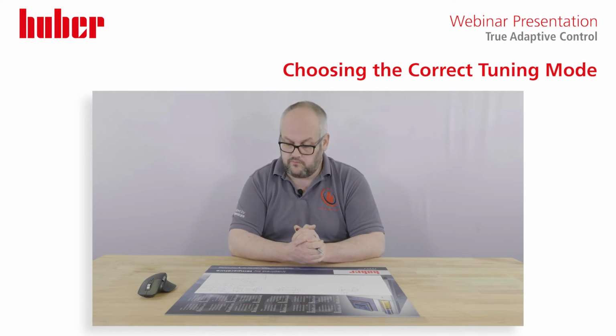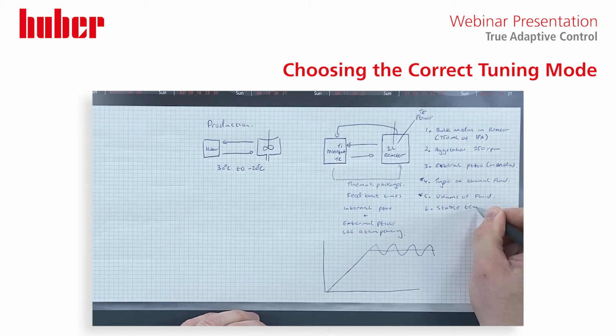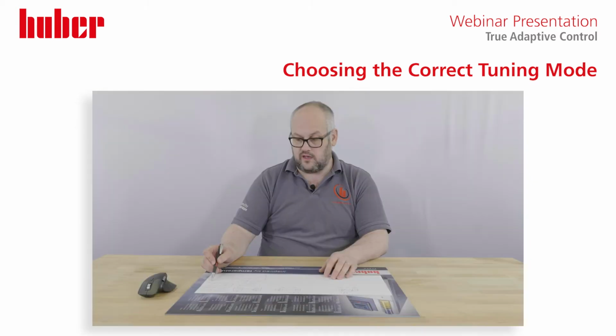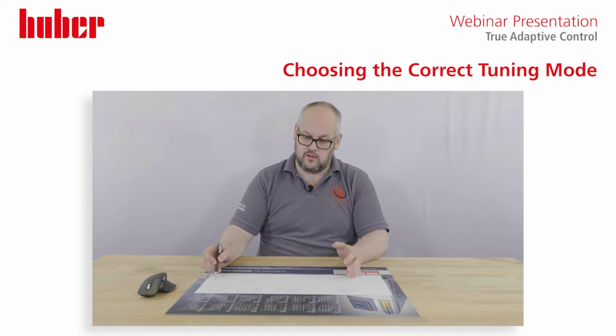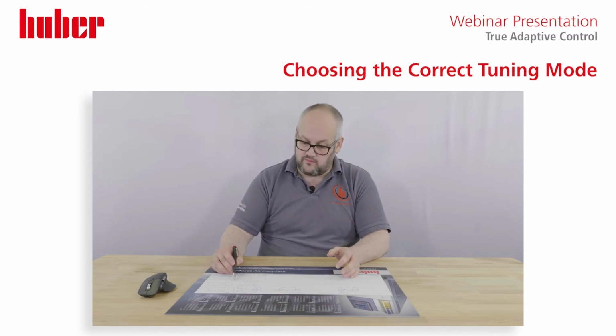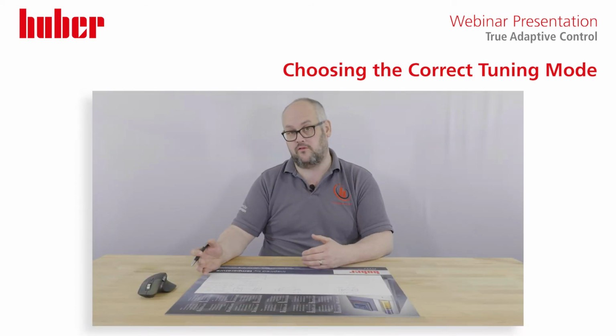So a key factor, which I should have mentioned at the start, was factor number 6, a stable temperature. With a stable starting temperature, we often tell people to run the machine for about half an hour beforehand when doing a fast identification loop tuning. So here you'll see we've also got a time lapse of a fast identification and the kind of messages you'll see popping up on the screen while it's doing its temperature control. You just leave it run. It'll tell you when it's finished. And if it cannot complete, it will also tell you that it cannot complete.